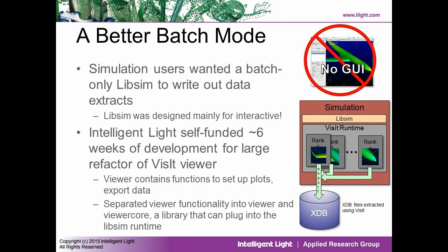The final big enhancement that we did was to add a better batch mode to LibSim. As Jim said, VisIt provides in situ, so you can load up the VisIt GUI, and you can connect to your running simulation as though it was just a regular VisIt compute server. So you can get the data from the server right into VisIt and explore it as it's going.